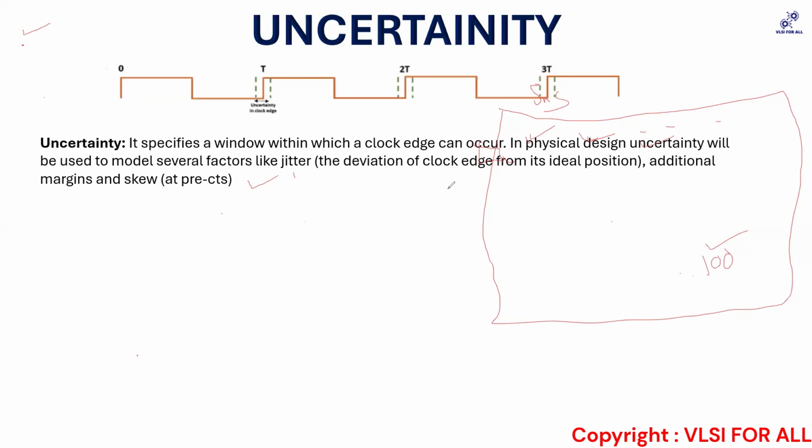So now you understand the uncertainty is nothing. The way I tried to explain it with respect to the person who is running a race, right? Similarly, the clock might start from the PLL. The time it might take can possibly be early or late, but we have to model it. We have to make the tool understand it. And whenever we are modeling it, that uncertainty every time you would have looked at is getting into your required time section.